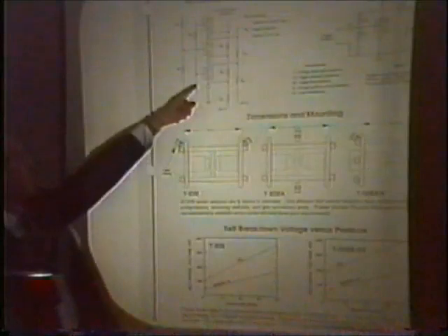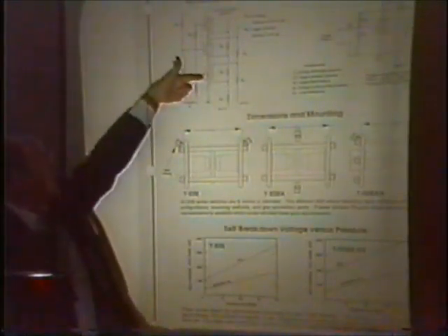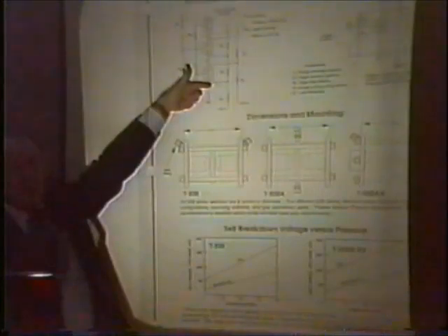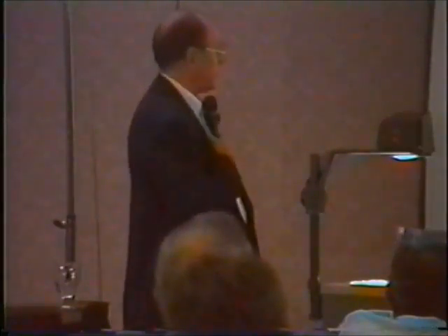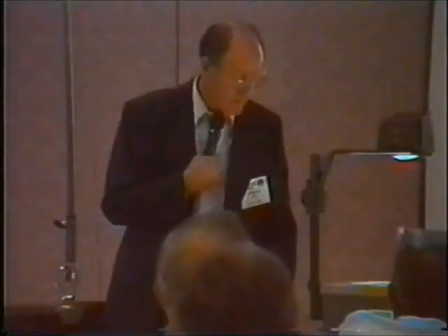And a Marx generator is composed, this is a schematic drawing of one of these things. So basically a Marx generator is a group of very high voltage and high amperage spark gaps with high voltage capacitors in between, and resistors. I'm going to show you an actual photograph of one of these next, where you can see it better.